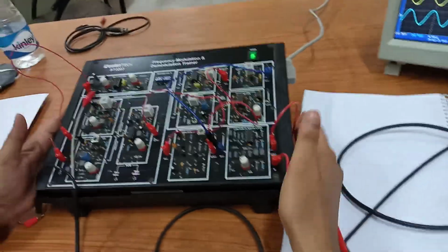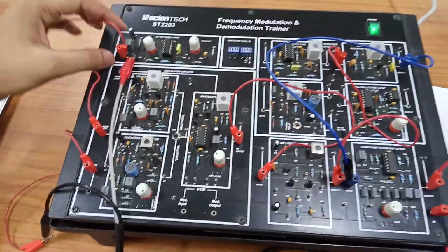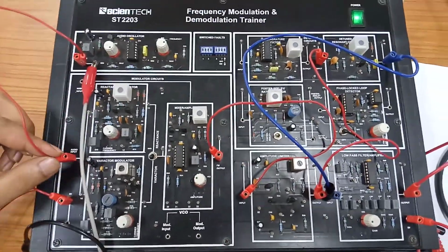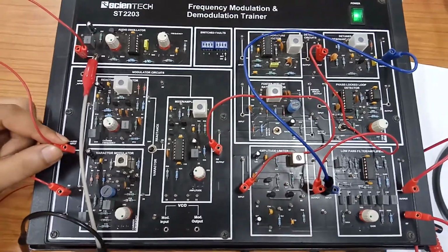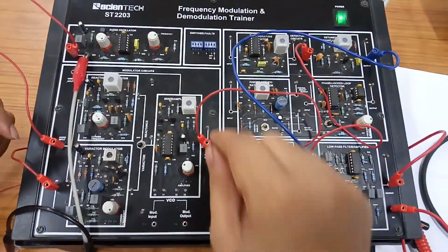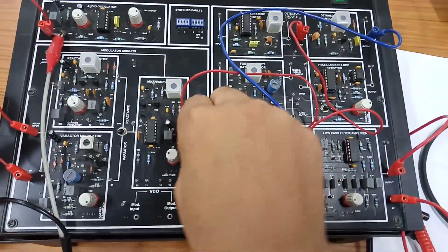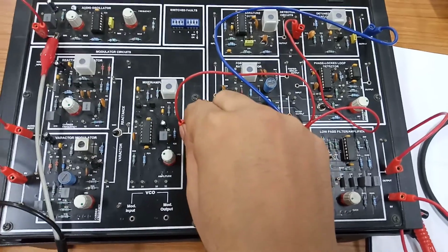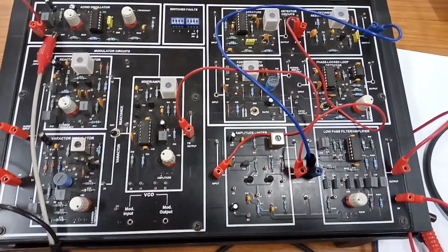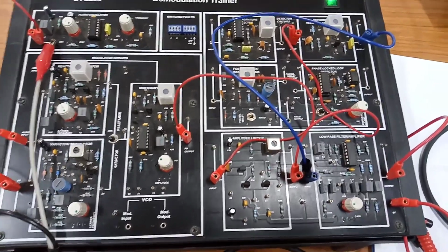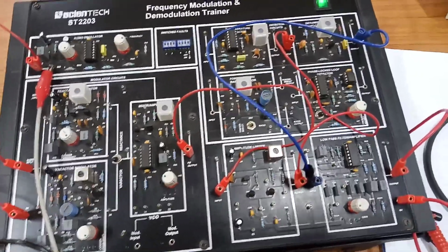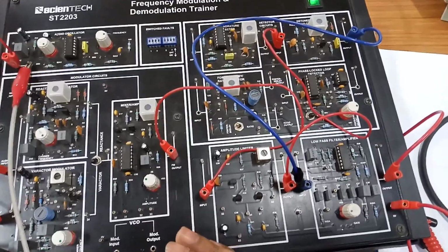So this is the circuit we have. We have produced an audio signal using an audio oscillator. We have given that audio signal as an input to the FM modulator circuit, where modulation took place, and after we got the modulated wave, we saw how the modulated wave looks as its frequency is getting changed. So the characteristic that changes for the carrier wave is frequency, as per the amplitude of the modulating signal or message signal. So this is frequency modulation.